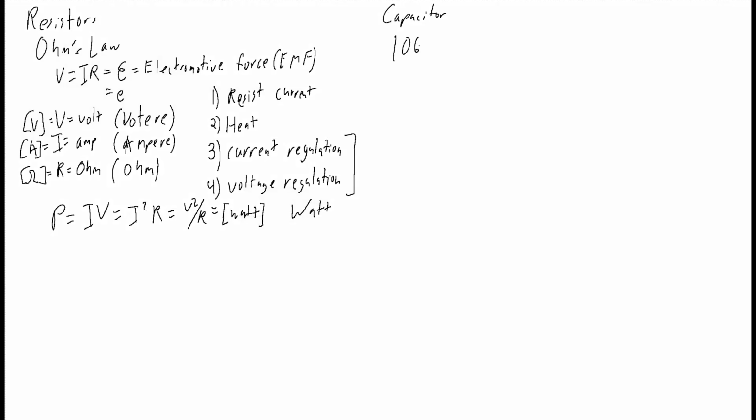Is that what was on there? No, 104. 104. That means that this is 1.0 times 10 to the minus 4 farads, which is 0.1 microfarads.